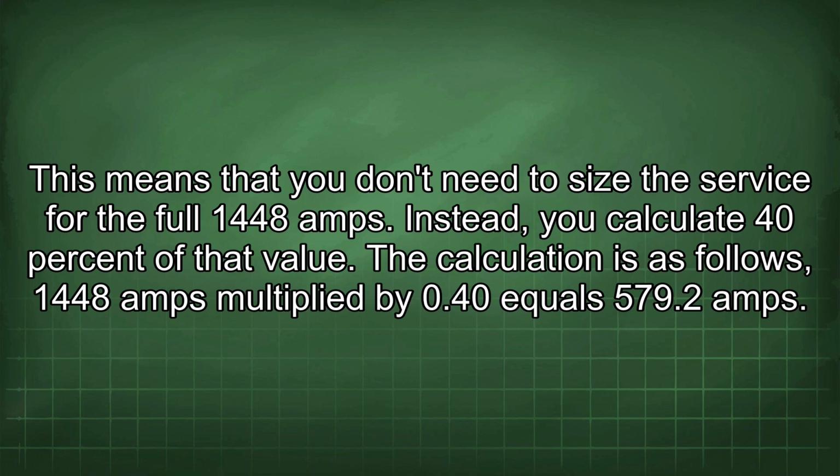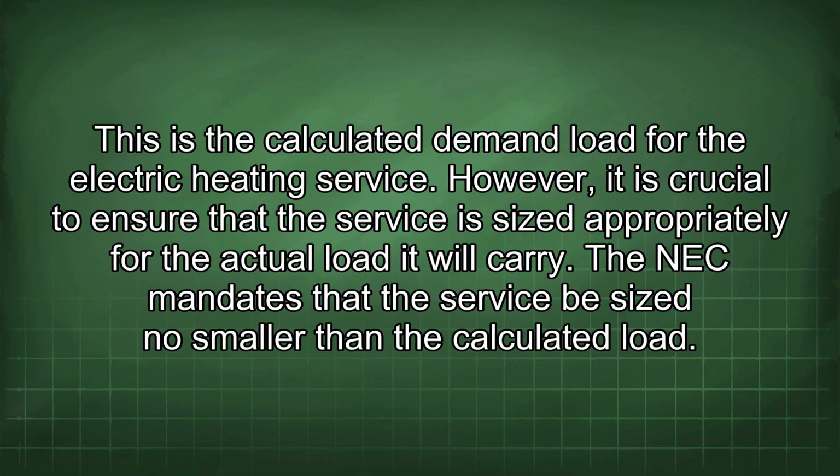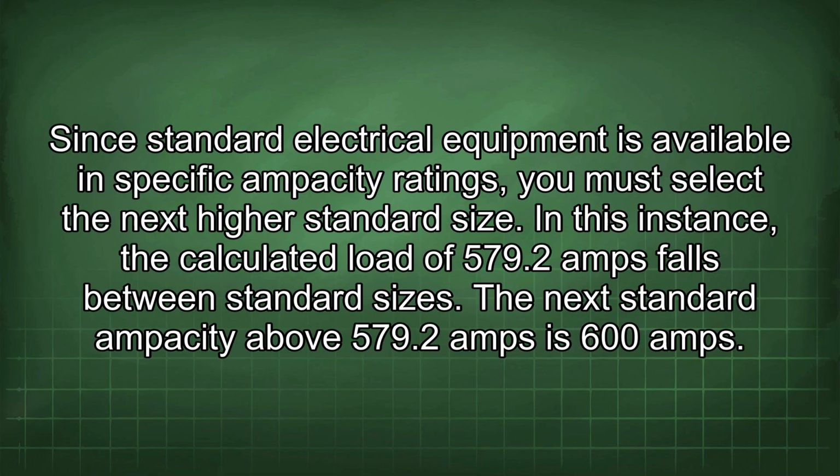The calculation is as follows: 1448 amps multiplied by 0.40 equals 579.2 amps. This is the calculated demand load for the electric heating service. However, it is crucial to ensure that the service is sized appropriately for the actual load it will carry. The NEC mandates that the service be sized no smaller than the calculated load. Since standard electrical equipment is available in specific capacity ratings, you must select the next higher standard size.